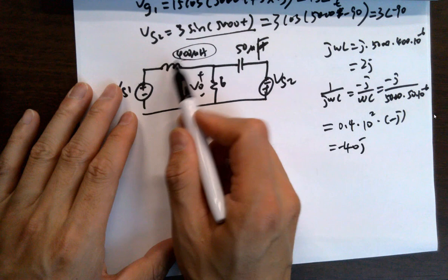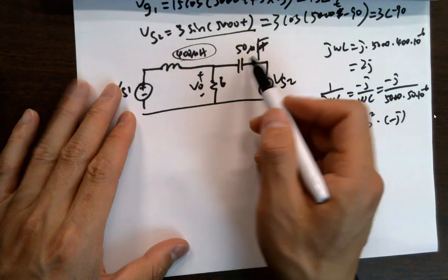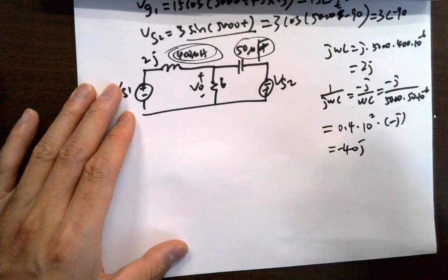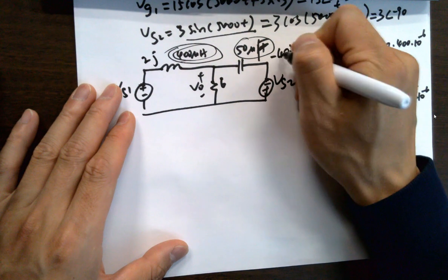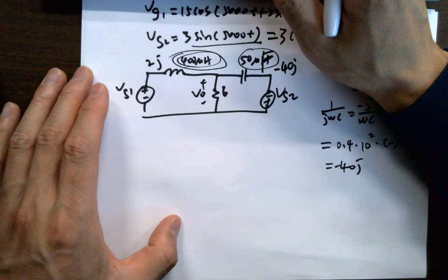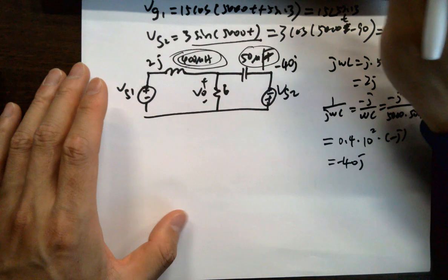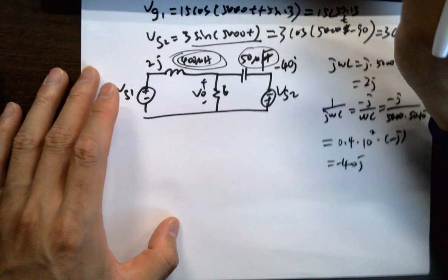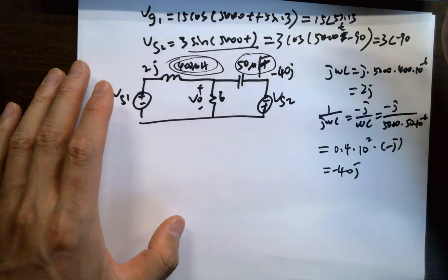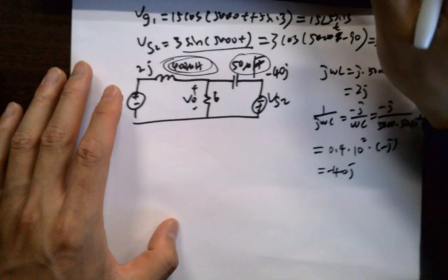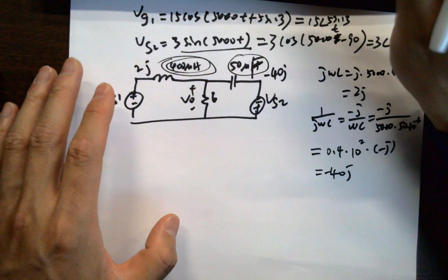So disregard all the inductance and capacitance. Directly convert it to its impedance. And then just use the impedance as a resistor and use the common circuit laws and theories you have learned in the beginning of the semester. Treat them as resistors. Never think about time domain. Only deal with phase and amplitude. You are going to have a problem like this in the exam. Just make sure you can do it.